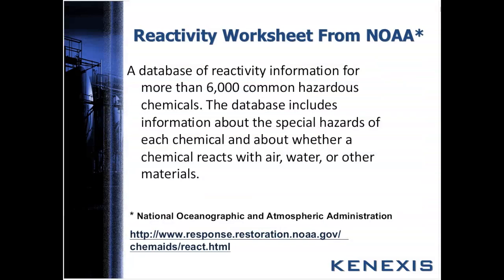one place you can find it is NOAA, National Oceanographic and Atmospheric Administration. You can go right on there and create a number of different matrices with various chemicals that you wish to react with. Also, you should include materials of construction, whether it be stainless, carbon steel, or elastomers that you might have in your process, to see what the impact of wetted contact might be with your materials of construction and your chemicals. Okay.